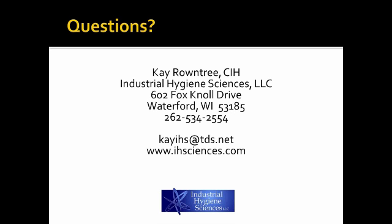Manual plasma cutting is a very dirty process and generates just tremendous amounts of fume. It's not unusual to have overexposures to lots of other metals. I have not sampled personally for that. I'd be interested if anybody else has data on that. I would say it's probably not a bad idea to establish what that exposure is, and just at least have some comfort that it's not a problem.